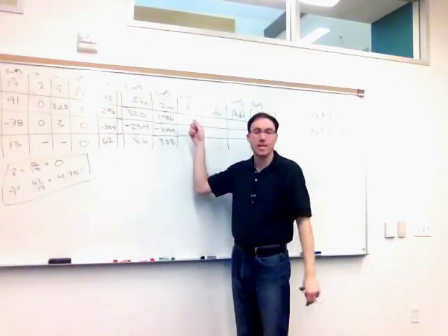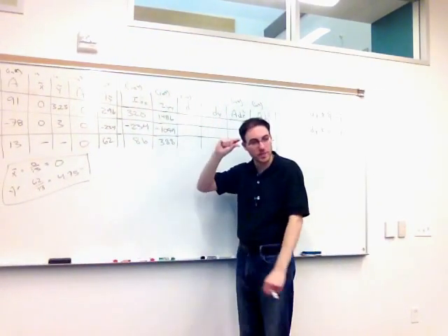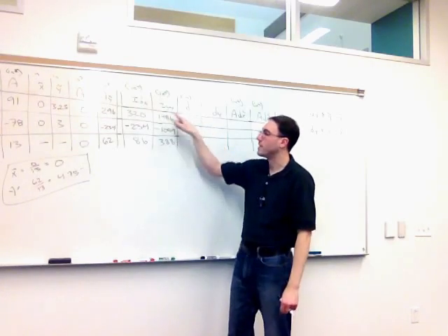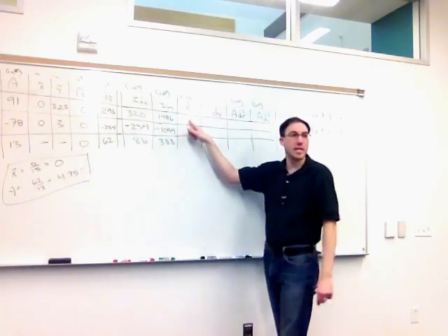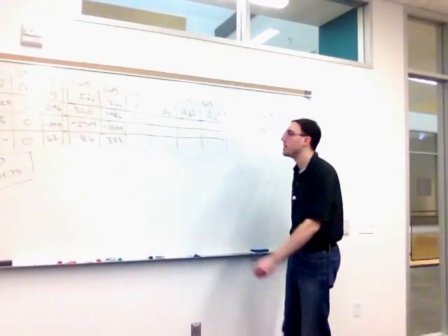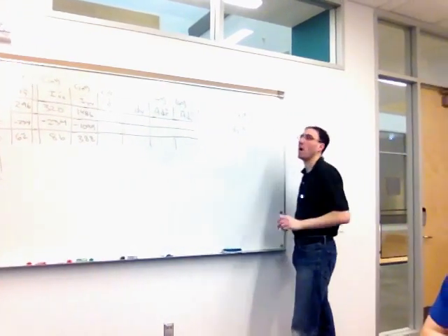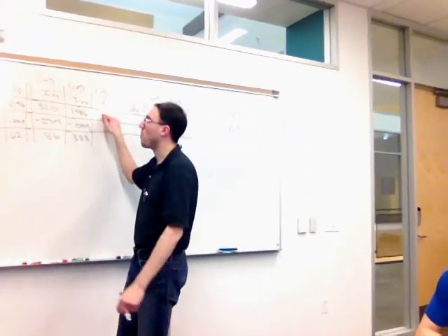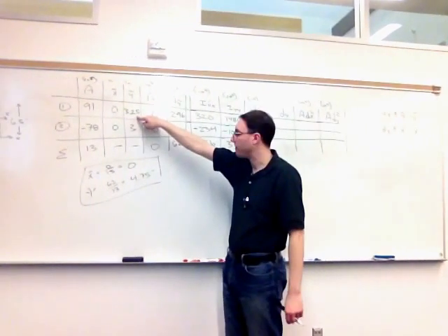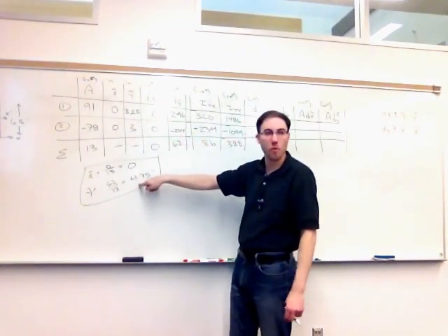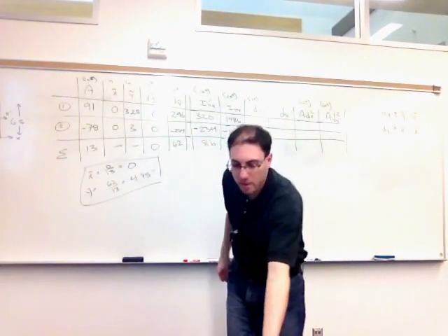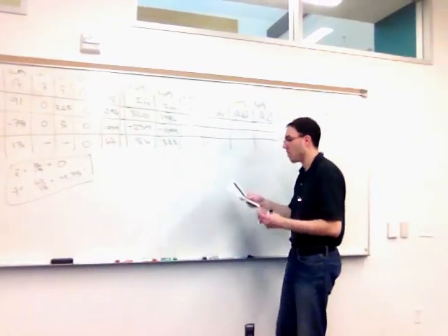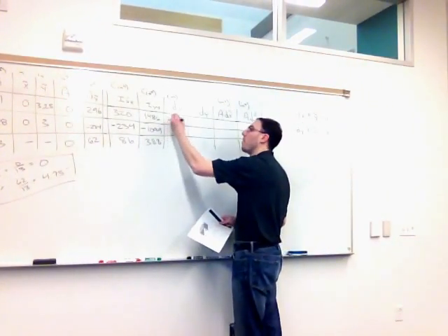Dx, again, this is the vertical distance between the centroid of, in this case, the first shape, and the centroid of the composite shape. That's why I'm using the y tilde and the y bar. For shape number 1, it'll be 3.25 minus 4.75. So I will get for dx for shape number 1, negative 1.5.